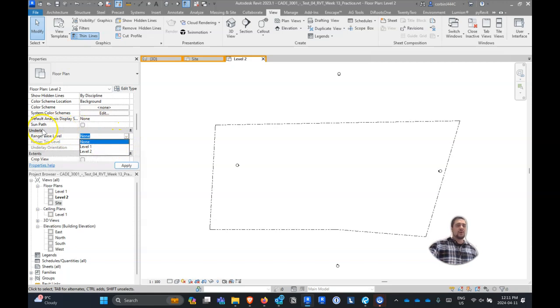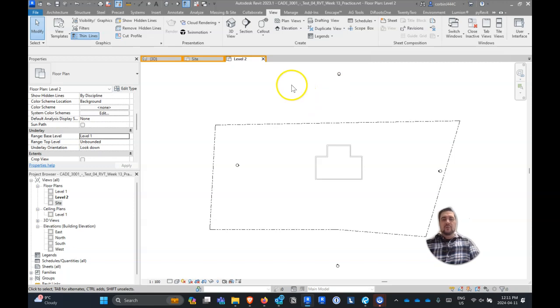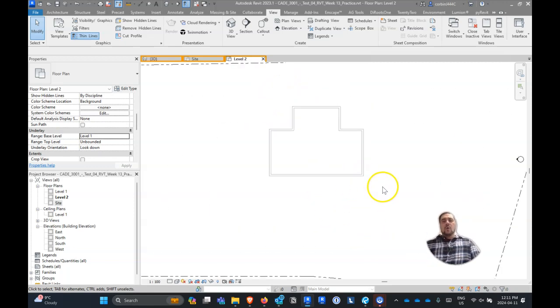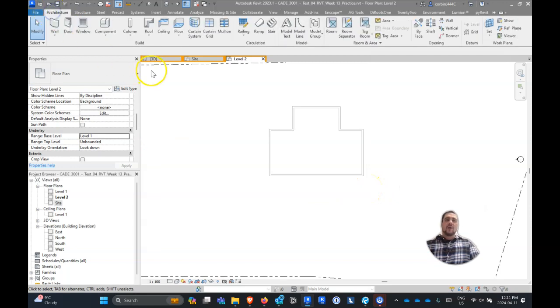So we're just going to turn on an underlay over here in our properties. Underlays are good, but I recommend being a little bit cautious with underlays. Make sure you turn them off because it can make your drawings not look the greatest. And so with that being said, we're going to start off with part of our roof. The part we're going to start off with is the main gable, so this longer part here.